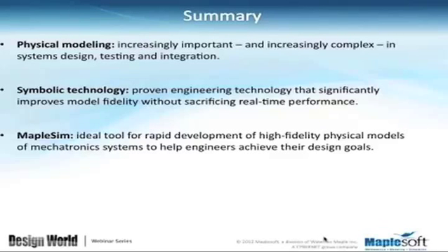Now, the only caveat here is that we only generate floating point code. So if the target controller has a floating point processor on there, then we can target that. If you're looking for tools to produce embedded code for fixed point types of applications, then typically the workflow would be develop the plant model in MapleSim and then bring that into a tool like Simulink or MATLAB, and LabVIEW to develop a controller from there.